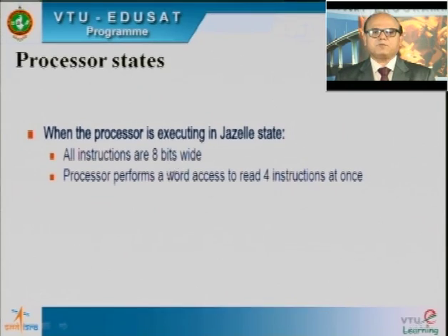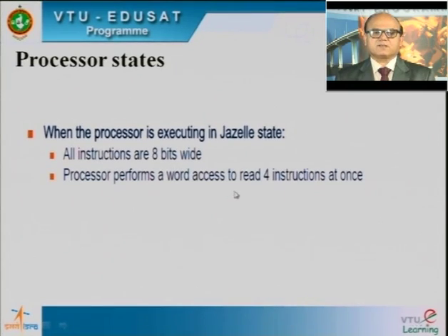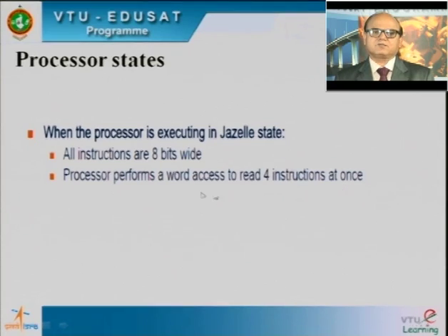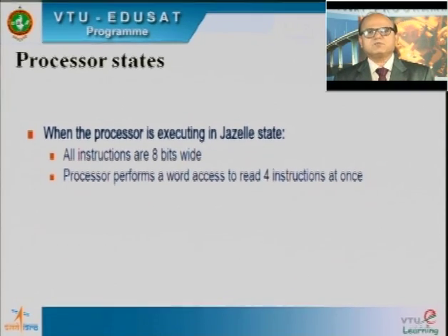The processor performs a word access to read 4 instructions at once. That means every access the processor makes is a 4 byte access. Naturally, in each access 4 instructions can be brought from the memory into the processor. So we definitely get the performance benefit.